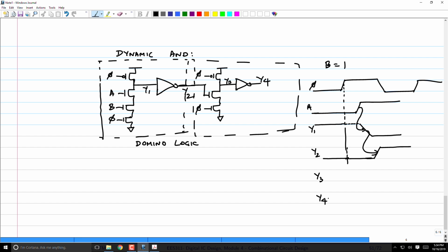No, here, okay, multiple NMOS I understand. Suppose, assume a trivial case. Assume the simpler case where there's a PMOS and there is only, without a footer, A. So what is happening is there is a capacitor here which is floating at VDD, right?